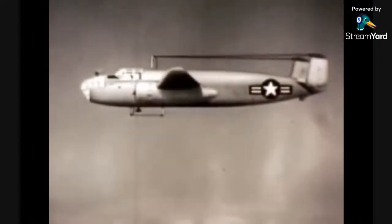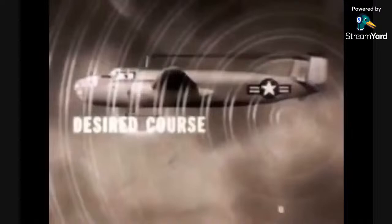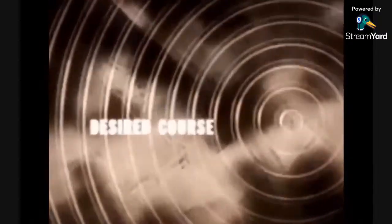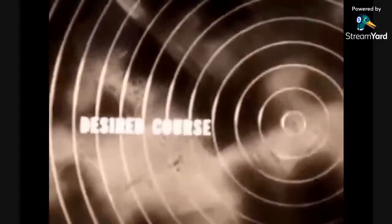While all aircraft have a radio set for command purposes, so too do they carry a radio compass. Its antenna receives energy within a particular pattern for air navigation. The antenna system is generally mounted forward under the pilot's cockpit. It is composed of a loop antenna and a sense antenna. The signals received by both are combined into a reception pattern resembling a cardioid. With such an antenna system, it is possible to readily determine proper flight direction.